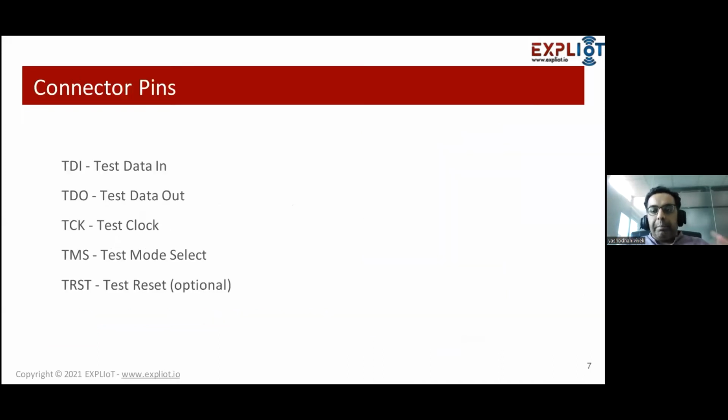Coming to the pins that we have, because this is something more important to us. The reason being, from the security perspective, these are the physical pins that the attacker will access, and eventually try to get access to the credentials or some of the important data in your microcontroller firmware. So here, let's understand those pins. As you see, the T always stands for test, so it's a kind of debug and test interface. But again, what is important is that we have a clock, so it's a synchronous thing.